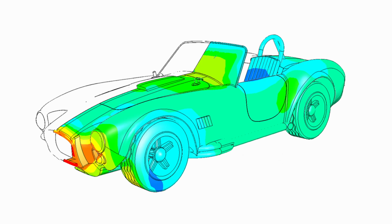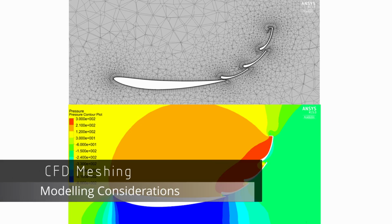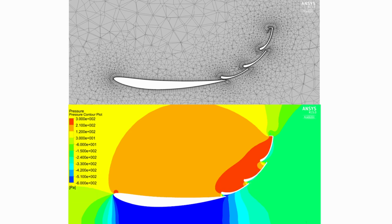For example, if I was to use a model for CFD, I wouldn't want to be including all of the internal detail there. And in order to create a reasonable mesh, I'd probably want a de-featured model. So it's very likely that I will need to have a separate CFD model than the main manufacturing model.